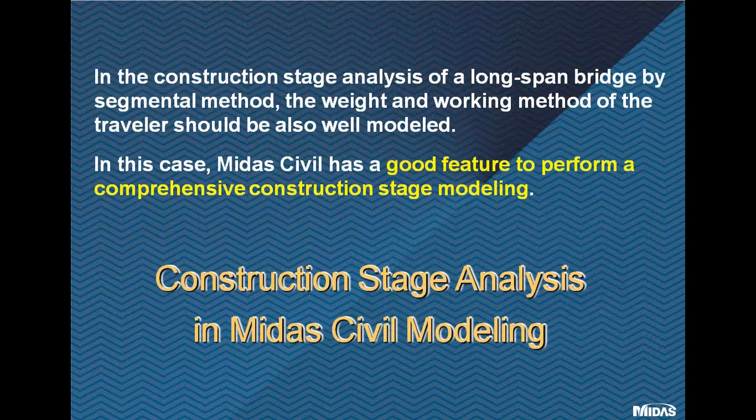In the construction stage analysis of a long span bridge by segmental method, the weight and working method of the traveler should be also well modeled. In this case, Midas Civil has a good feature to perform a comprehensive construction stage modeling.